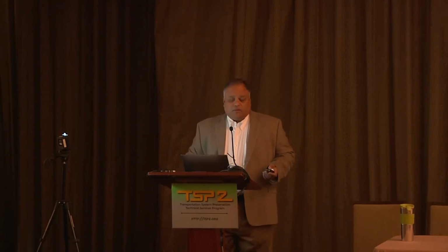So it's really important to know where those critical areas are, and if those areas are corroding, you need to address that immediately, right? Otherwise, in general, if it's a compression member, concrete is good in compression, right? You can sit and wait a little longer to address those things.